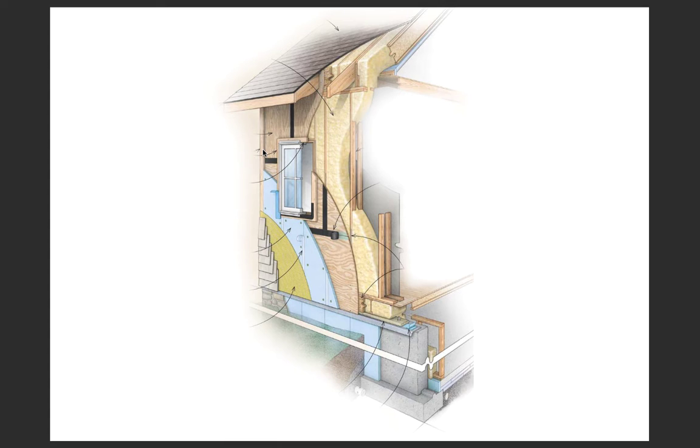Because constructing details, at the end of the day, is all about protecting your construction from water, from any type of water, whether that's vapor or liquid form, because that's what eventually causes damage within your construction if you're not in control of it. At best, it is causing problems within your insulation by making it inefficient because it's getting damp, so it doesn't have the same properties anymore. So yes, unfortunately that demand for a controlled climate has made things a little bit more difficult.